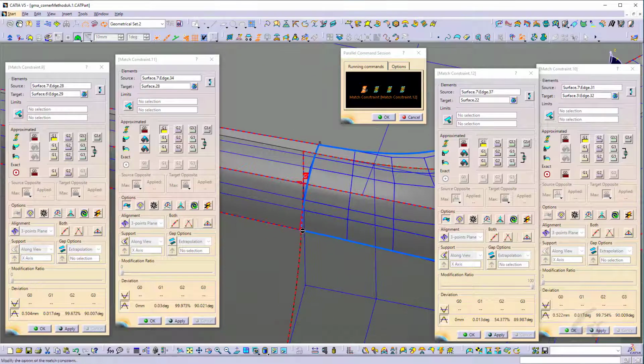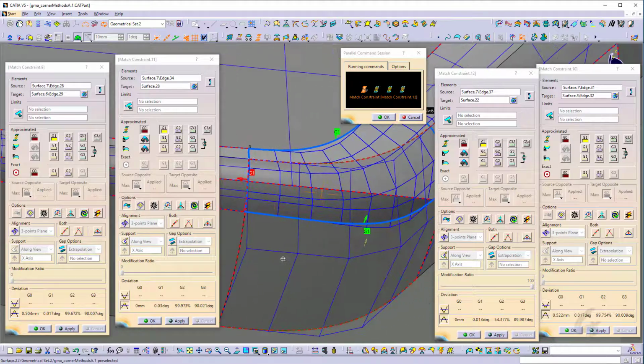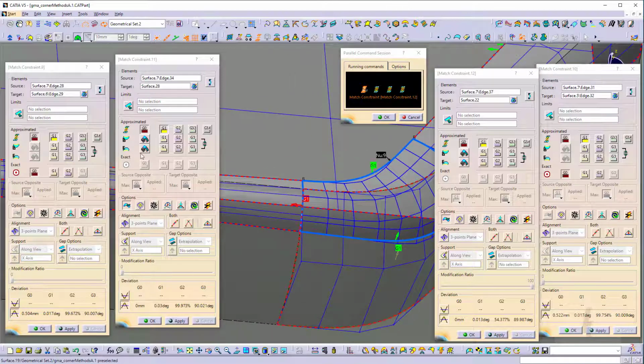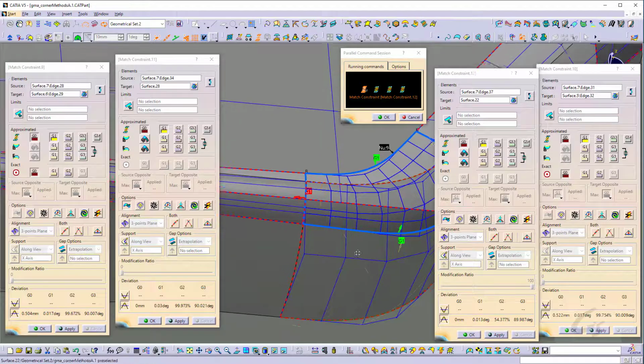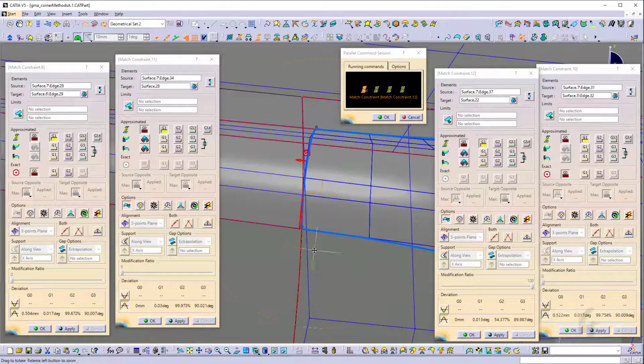And this is where it's an advantage to use a parallel command session because I have instant access to all the dialog boxes to quickly find out what's wrong. This scenario is kind of like chasing an air bubble. When I make one correction to a match, it destroys another, and vice versa. So, this just tells me of 2 possible causes. One, the adjacent fillet is out of tolerance to its support surface, or two, there is a sliver gap or maybe an overlap with the corner fillet edge to the adjacent fillets.